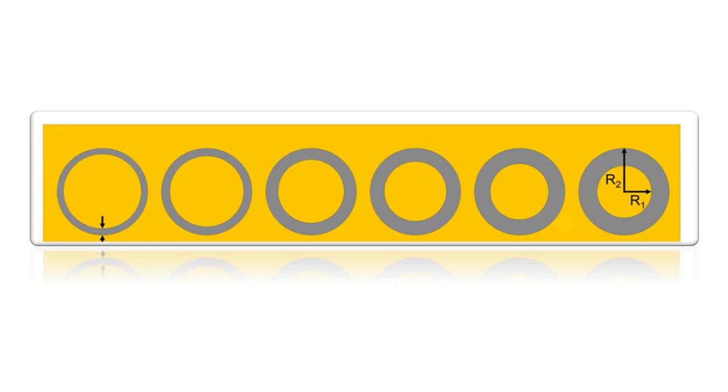The circular transmission line model technique is widely used to measure the contact resistance in semiconductor devices. It's really important to understand the CTLM structure. So, for example, here is the CTLM pattern. The CTLM structure consists of a series of concentric circular contacts on a semiconductor surface. The contacts are typically metal pads deposited on the semiconductor material.